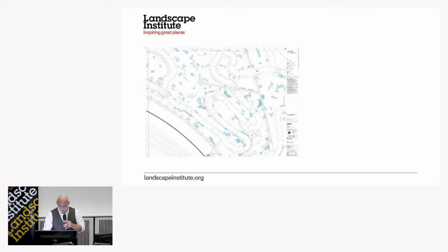we were actually able to export the data from the GIS and produce a series of X-reference files that will go into AutoCAD that would feed the 500 planting plan drawings, and they were split by types and different locations within the site. But essentially, 600 drawings were generated automatically without any human input whatsoever. Not once did we have to go into any of these drawings and manually alter them. It was all done from the workbench that I showed you just a minute ago. So straight away, the time savings on that, just from using a BIM workflow on a single source of data, was phenomenal.